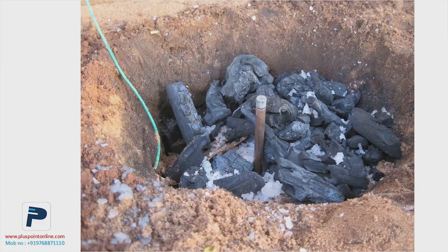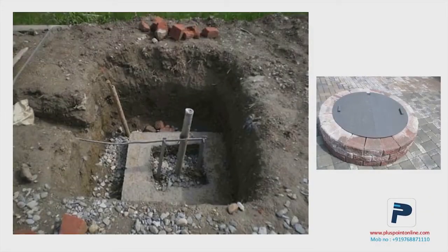Apart from this, sometimes they also place coal or salt around the rod before leveling up the ground. To speak about some good ways of very good earthing, sometimes after finishing the earthing, they make a brick wall like this around it. For example, after finishing rod earthing or plate earthing, this wall structure is built around that. There is no standard way to do this and it requires more labor as well. So brick earthing is also another form of traditional earth pit.